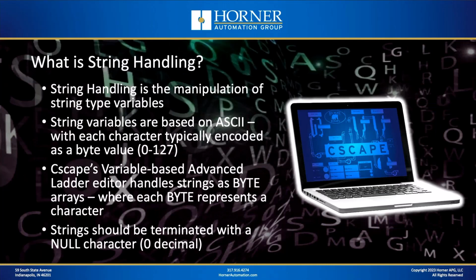So what is string handling? Well, string handling really is the manipulation of string type variables. And what are string variables? Well, string variables are based on ASCII, character-based communications, where each character is typically encoded inside of a byte, at least the first 7 bits of the byte, because most ASCII characters have a character code between 0 and 127. Now, in variable-based advanced ladder that's built into Cscape, it handles strings as byte arrays. So every character is represented by a byte, and a string of characters is represented by a series of bytes through an array.